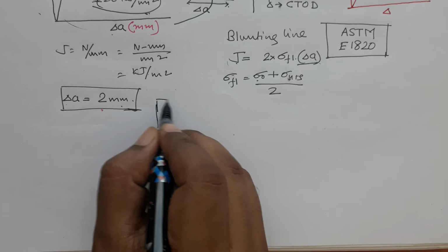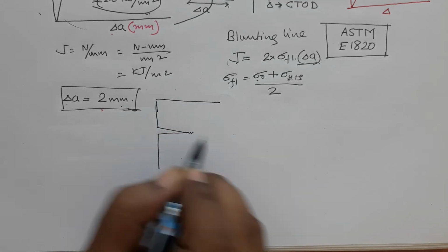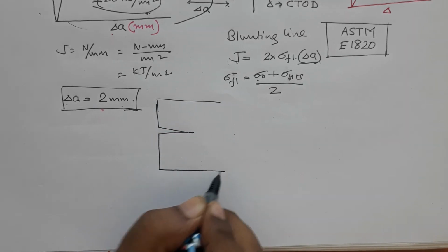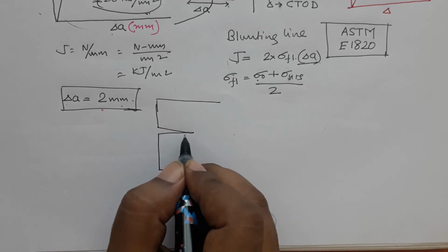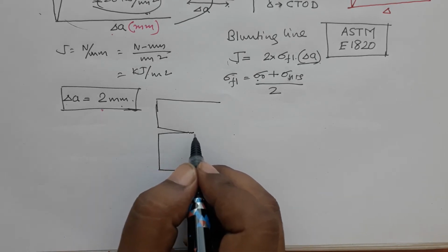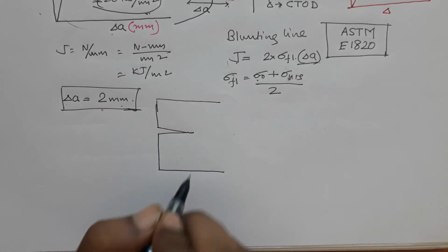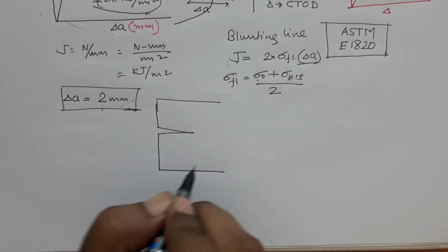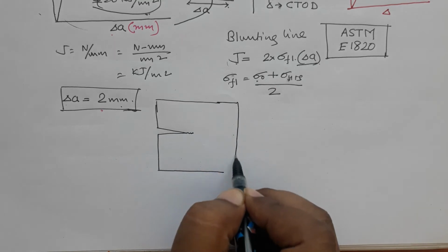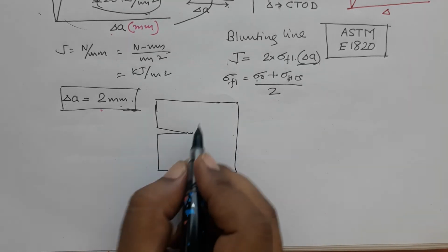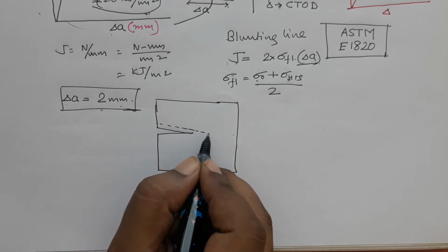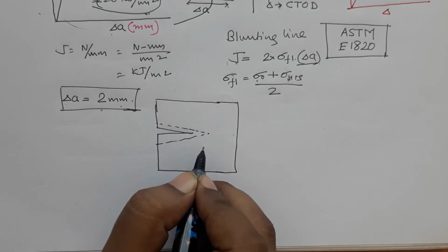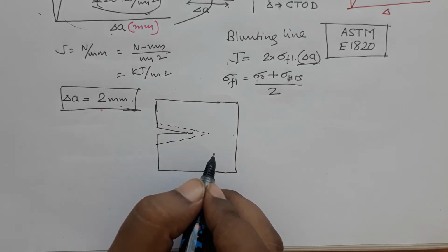How do I make the pre-crack? That part we have discussed, that I do a fatigue loading and I make a sharp crack, and that sharp crack has come from fatigue or cyclic loading. So, that is called fatigue pre-cracking, right. Then I loaded this specimen. After I loaded this, there will be some crack growth, right, or some amount of blunting or some crack growth.